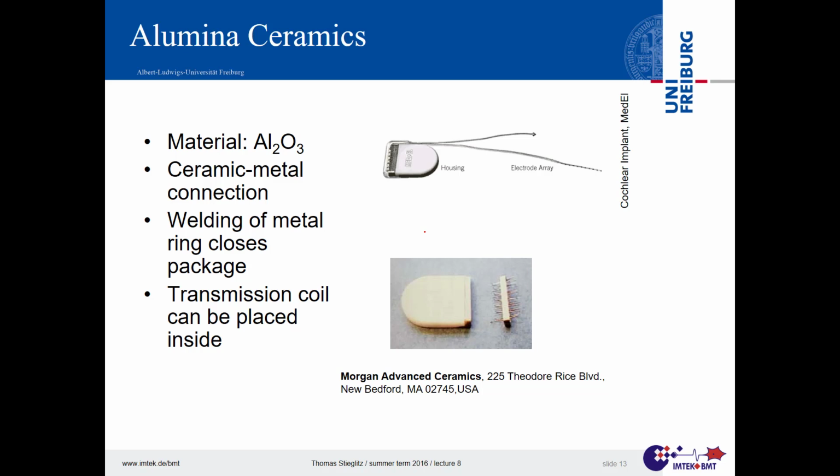So I have old movies where we try to make our first ceramic packages stable, and what we have seen was a huge mess, because that 2 joule hammer is really strong, and we destroyed a lot of packages by bumping that hammer into our packages. So 2 joule is doable, 4 joule is really a challenge for ceramic packages. Probably you can argue something.